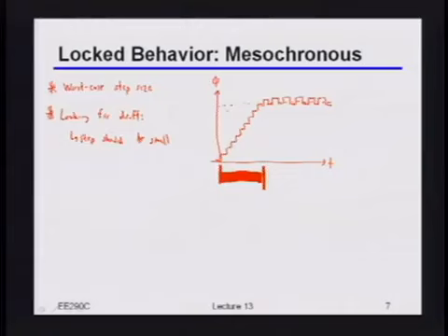Does making the step size small affect the time it takes for you to actually get to the right point? Yeah, absolutely, right? So indeed, if you make those step sizes very small and you don't do anything else, then initially when you have to cover a very big distance, it's going to take you a long time to cover that distance. But imagine that once I'm in lock, basically the only thing that tells me how big to make these steps is how big the residual errors I'm trying to track in the first place were, right?